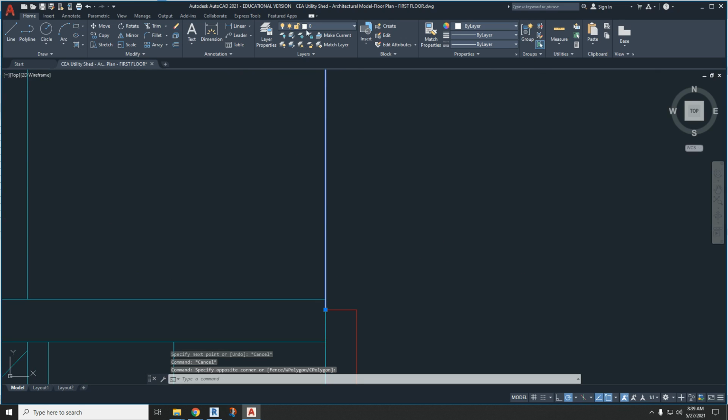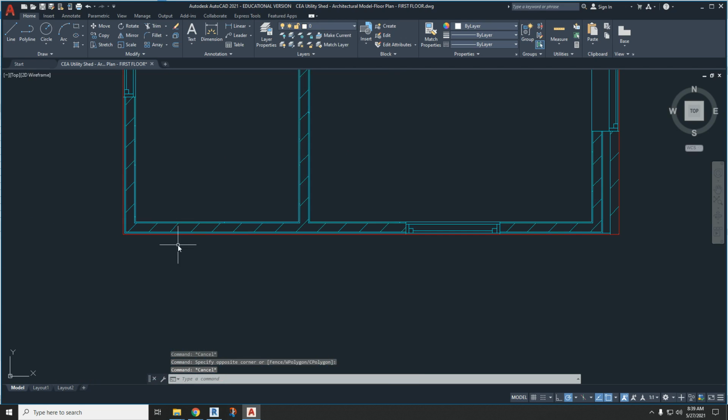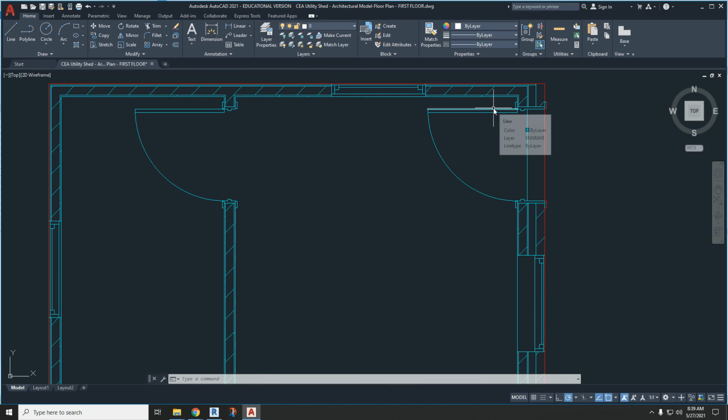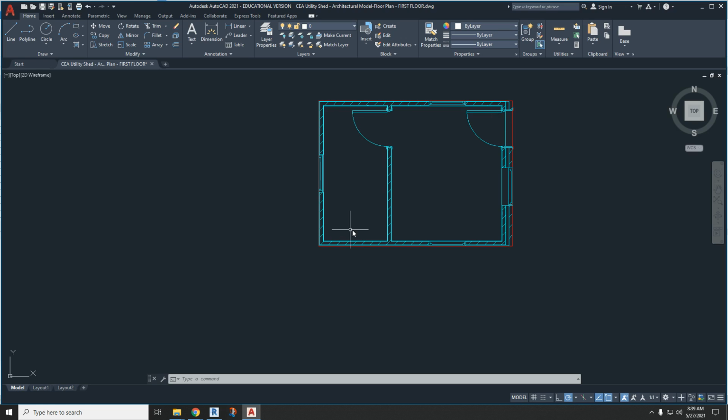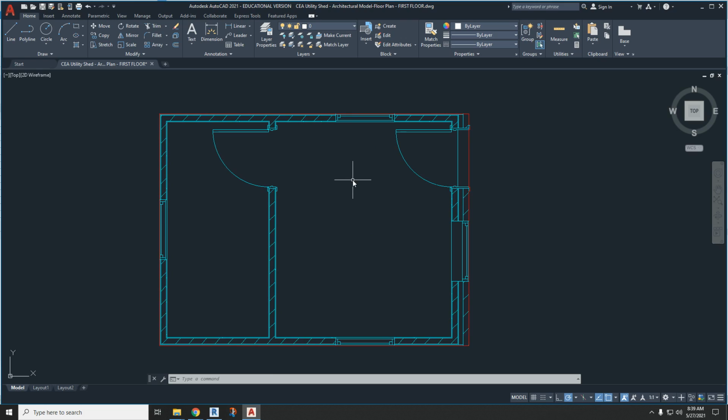Oops, I forgot to switch my layer to cut. So I'll just highlight the line. And now you can see all around the border here, this will cut it out of the foam board. Everything else will engrave, or just slightly burn into the foam board. That's what I'll set the blue layer to. Everything else will just cut.